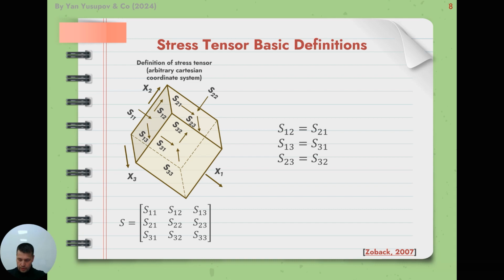In the context of continuum mechanics, the stresses in a homogeneous and isotropic medium can be described by a second-rank tensor with 9 components. To fully describe the stress state at depth, one must define either 6 stress magnitudes or 3 stress magnitudes and 3 angles that determine the orientation of the stress coordinate system in relation to a reference coordinate system, such as the geographical coordinate system or the wellbore coordinate system.